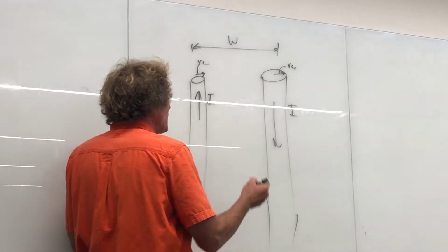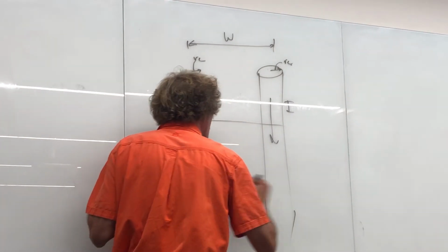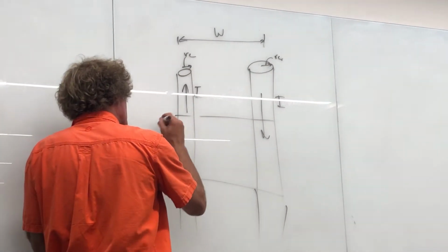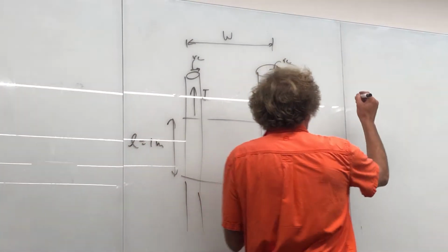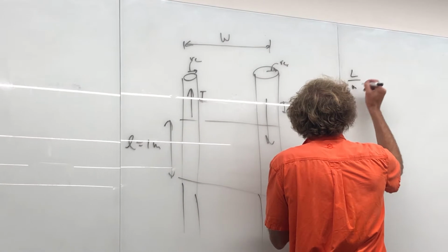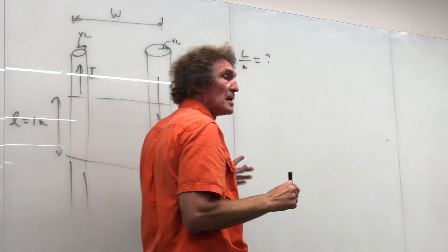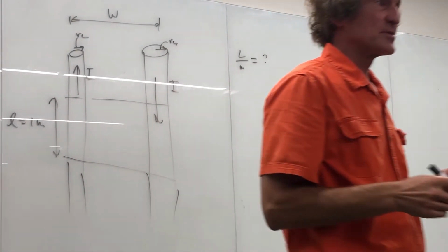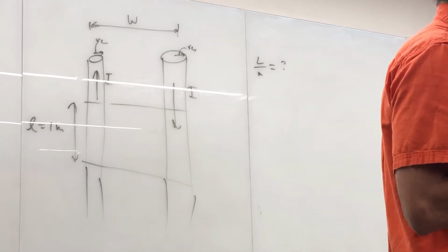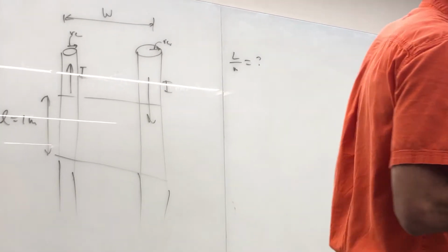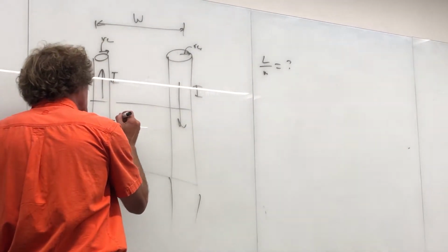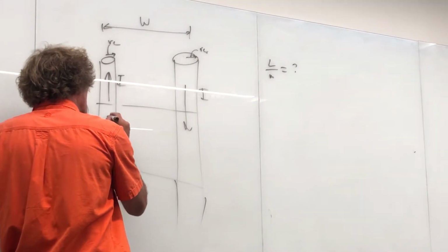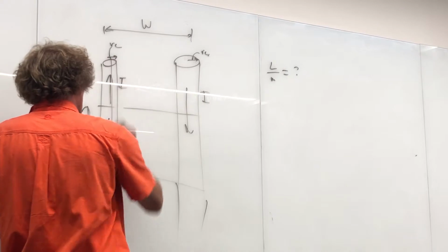All right, now if I want the inductance per meter, so I'm gonna say the length here is gonna be 1 meter, and I'm looking for the inductance per meter of this system. I've just showed you the currents. These are currents I've assumed because I'm trying to calculate this inductance. So we start out by saying, well, what is the B field here at any given point? Let me take this as my z-axis, right?